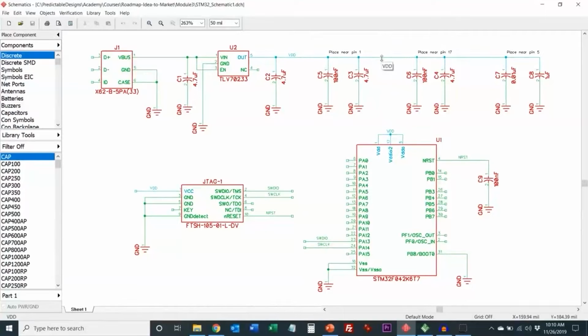One easy way you can see here is when I highlight one of them, all of the nodes connected should also highlight. The other components that are on here are the capacitors. The passives are going to be capacitors, resistors, and inductors. Inductors tend to be more rare. That's probably the least used of the passive components. They're typically going to be used in switching regulators and for filtering.